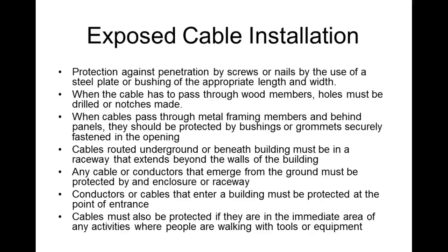Conductors or cables that enter a building must be protected at the point of entrance. Cables must also be protected if they are in the immediate area of any activity where people are walking or driving over. So most of this stuff is pretty much just common sense, right? So conduits are in there to protect the conductor, but we also got to protect the conduit too.